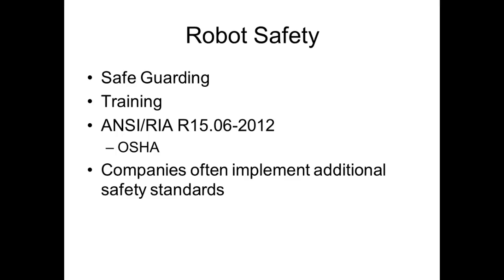You can have a lot, but it's up to the company. RIA only says you have to have at least two: one on the controller, which is the computer that runs the robot, and one on the teach pendant, which is that little computer you hold in your hand to teach the robot, to do what we call online control.